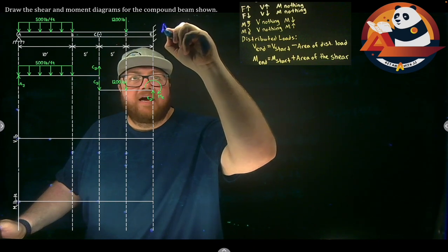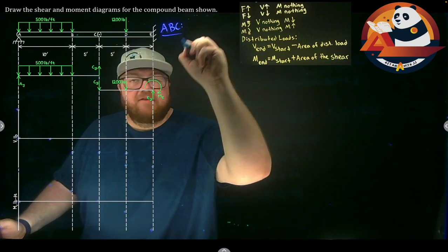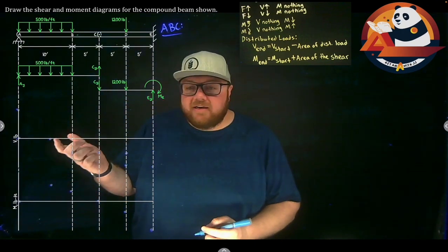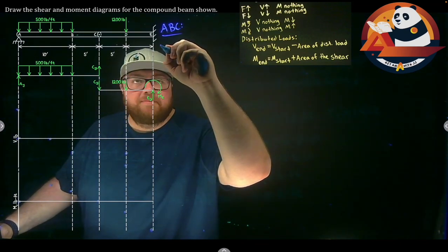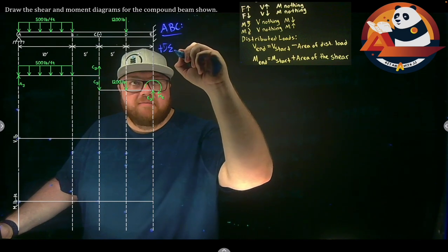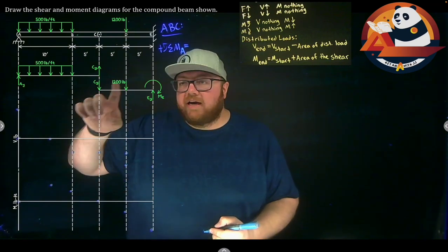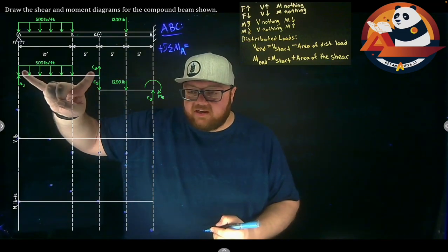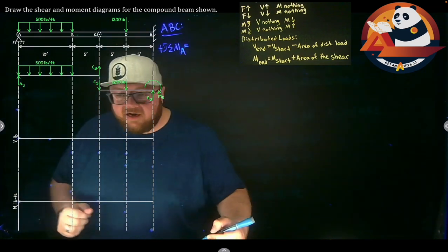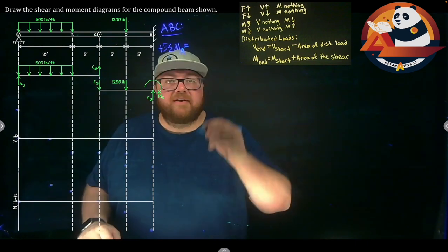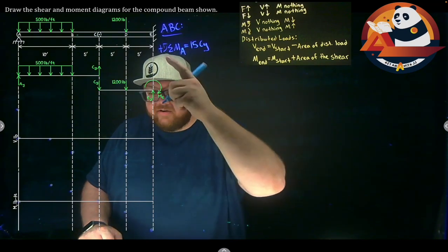So if I'm looking at A, B, C, we have our free body diagram drawn out, and I can just come in and say, well, let's find moments. If we do moments at A, I can find CY. So with positive going counterclockwise, summing my moments about point A is going to get me, well, CY will cause a counterclockwise rotation. We're working with the top free body diagram here. So it's going counterclockwise about A, and it's 10 plus 5, 15 feet away. So 15 CY. And then we'll get the rest on the next line.